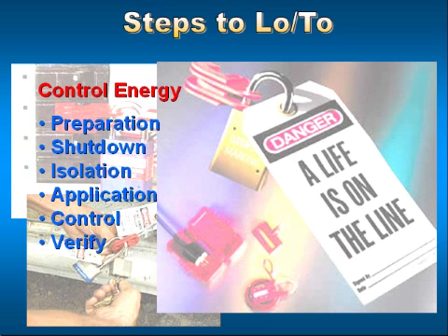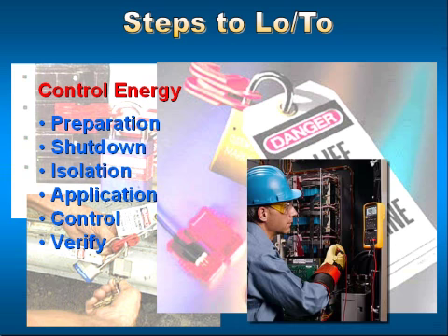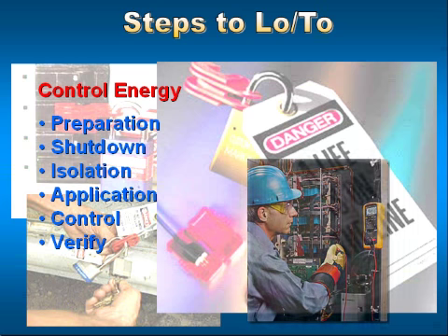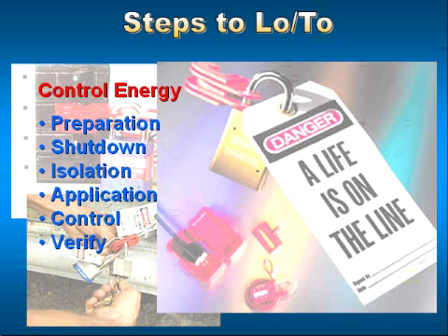These devices are commonly referred to as widowmakers, and they're called that for a reason, because sometimes they function and sometimes they don't. There is no instrumentation associated with them. And should they be defective, or should they not get a sufficient enough reading, they wouldn't flash. You would think it was de-energized and now expose yourself to potential risk.